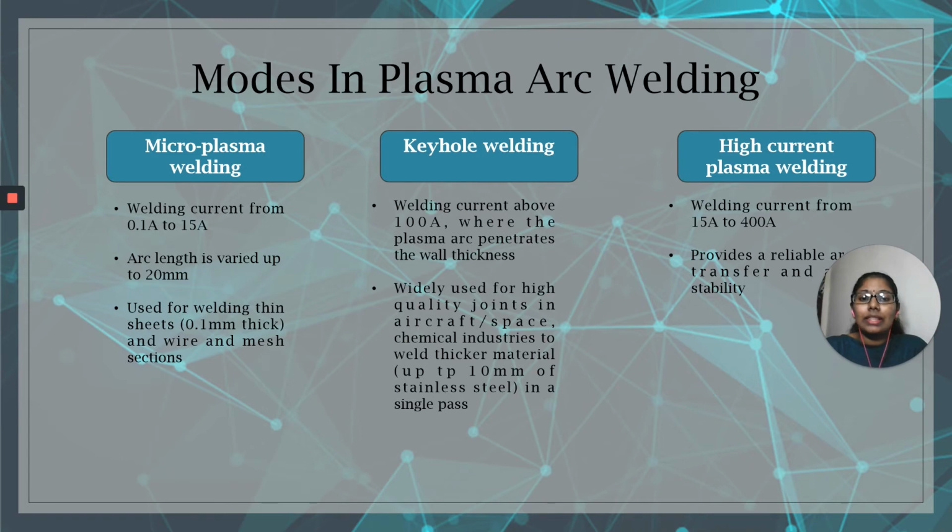In very thick material, a joint design is needed to reduce the thickness of the material, and multiple passes in non-keyhole mode are needed to fill the joint.